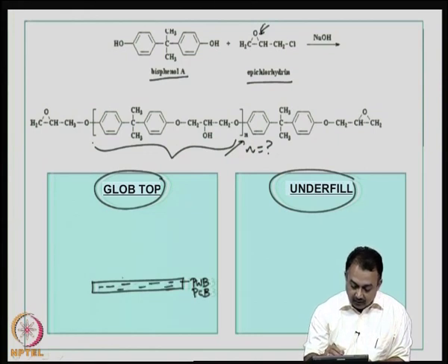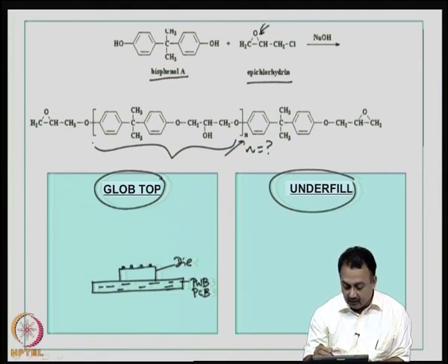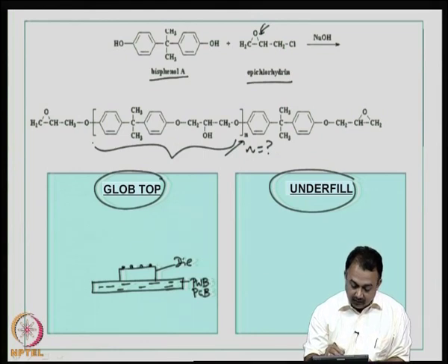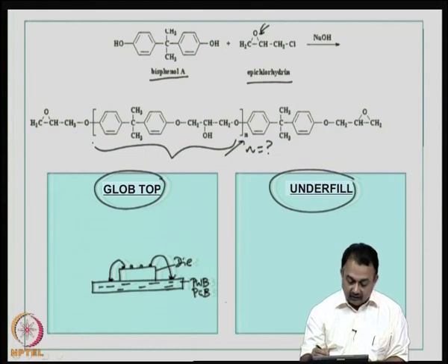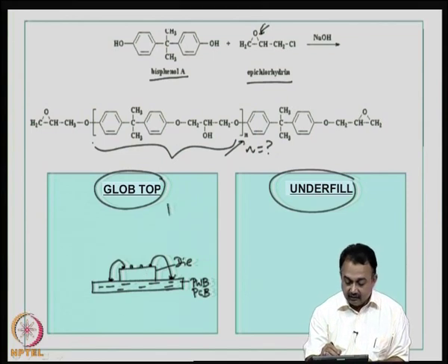Now, here you are going to place a die, a known good die, on top of which your bond pads are established or the IOs are established. Now, peripherally you do a wire bonding. So, you require bond pads on the substrate also. Now, you check your wire bonds for electrical contacts. Now, for this particular bare die where the face is up, this is a face up configuration.